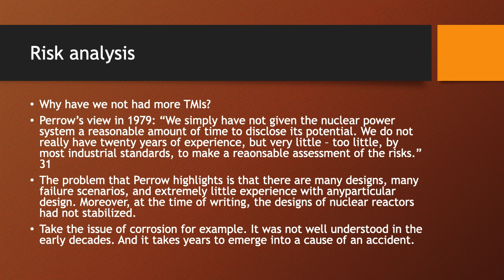One interesting example, I think he makes use of this example, but in any case it's an interesting one, is the fact of corrosion. And evidently corrosion occurs much more rapidly in plumbing under conditions of high temperature, high pressure. And so a plumbing system in a nuclear power plant that was designed to last, let's say 25 years, may be hopelessly corroded after 4 years. And this was not planned for, it was not taken into account. And it means that there are new failure hazards in power plants which were not expected, not intended, and now need to be ameliorated.